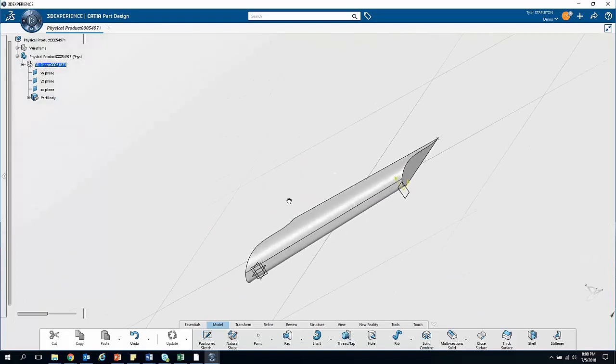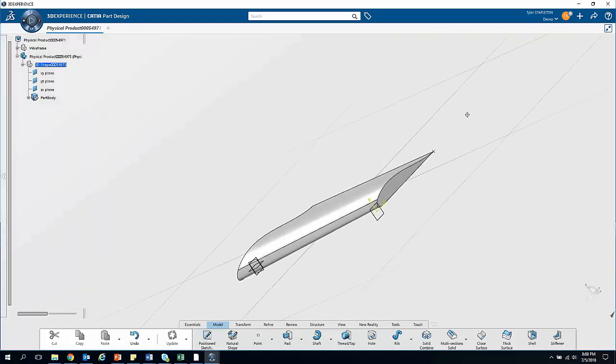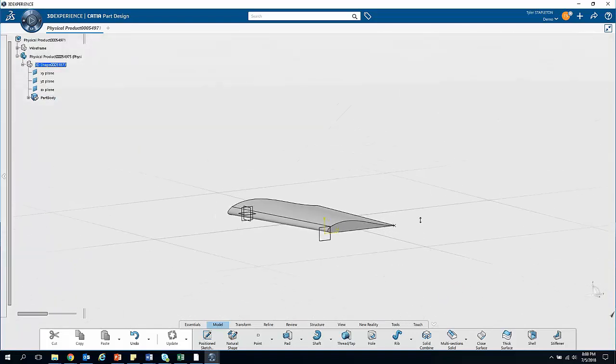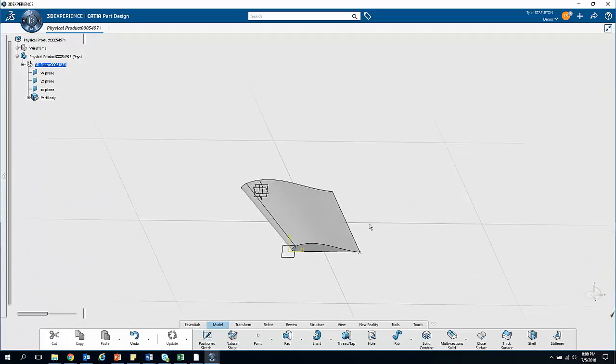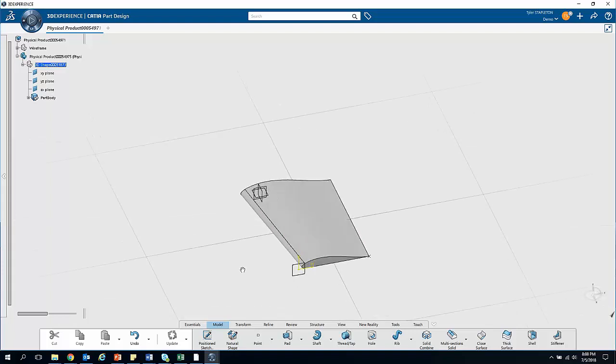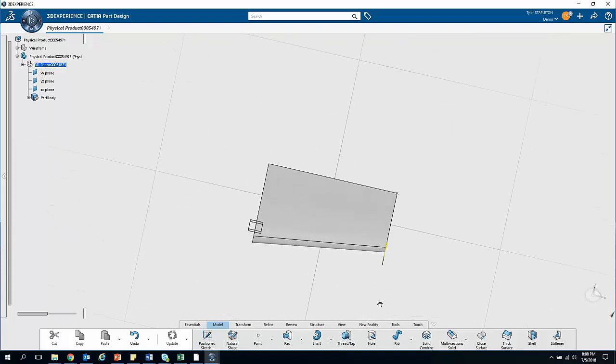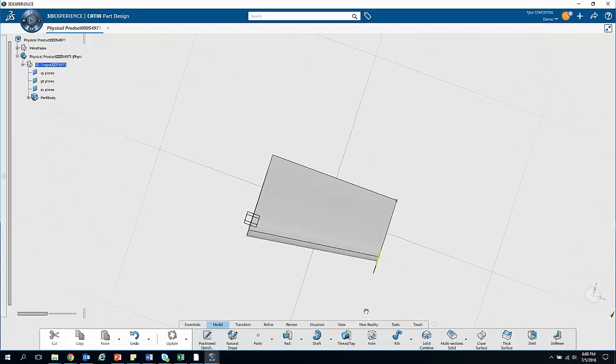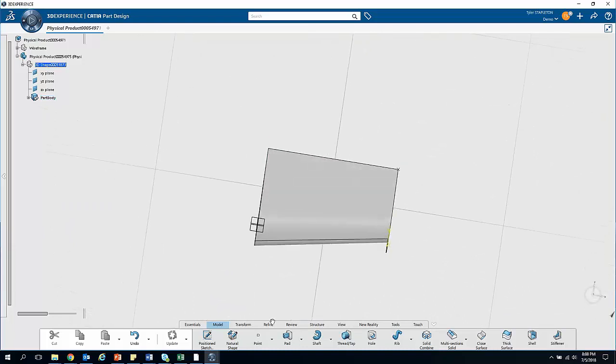These types of tools become especially useful when you're dealing with airfoils because airfoils are very difficult to draw, very difficult to scale by hand. But you can do it this way and very quickly get a nice tapered wing like I've created here. Now obviously this wing is way too stumpy, but I wanted to make sure that you can clearly see that it is a tapered wing, and it does get scaled down.